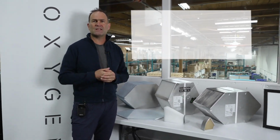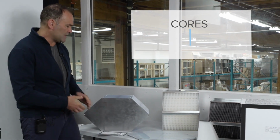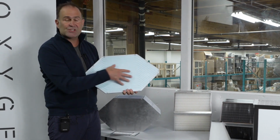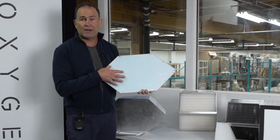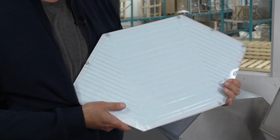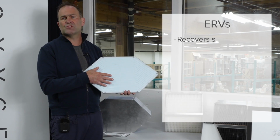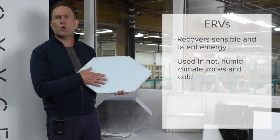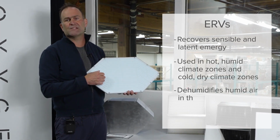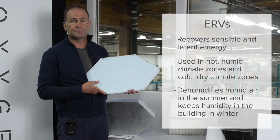And there's two main types of cores. There's ERV cores and then HRV cores. So ERV cores will have a membrane inside. In this core here, you'll see the blue material is a polymer membrane, which transfers both water vapor and heat, or does sensible recovery and latent recovery. This is really used in hot, humid climate zones and cold, dry climate zones, where you want to dehumidify that humid air in the summertime or keep the humidity in the building in the wintertime.